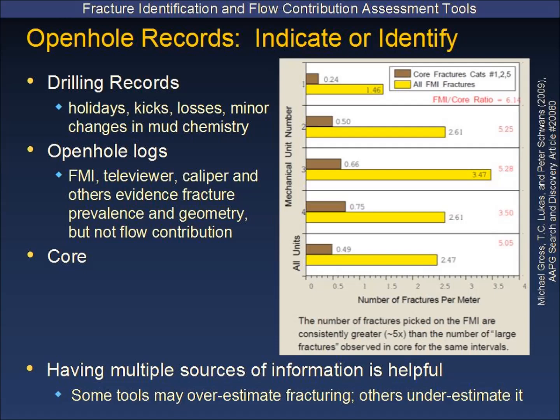Mud logs, smell. Were there changes in the chemistry of the return fluids in selected intervals that might indicate differing fluid compartments interchanging over a single depth interval? Now, this doesn't work very well for fine-scale fracturing as the signal gets too diffuse in the return mud stream, and it certainly works best if you're drilling close to balance. But I have used it before to identify fault intersections and larger scale fractures.